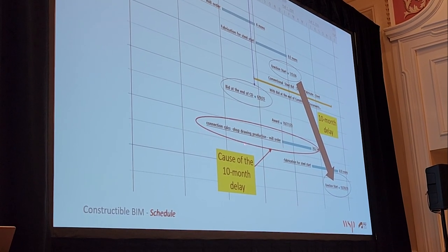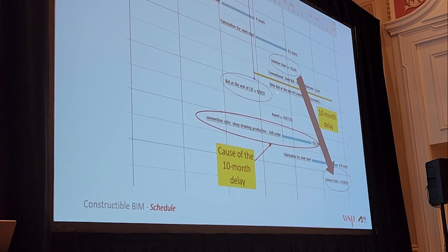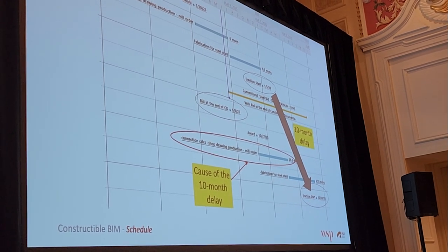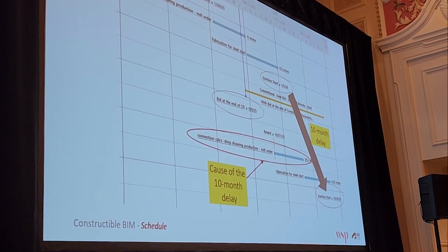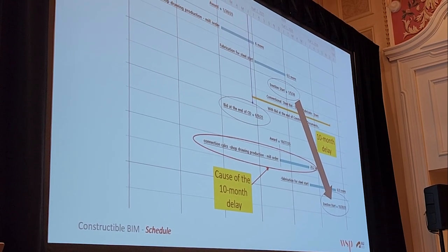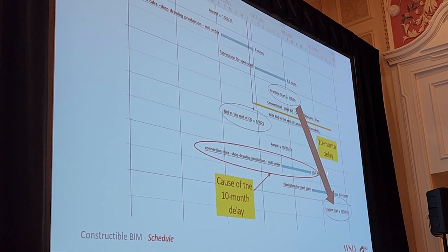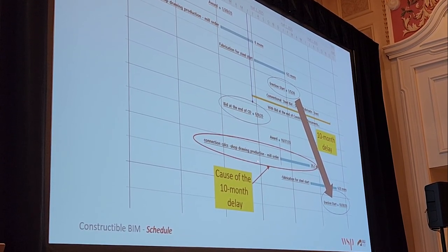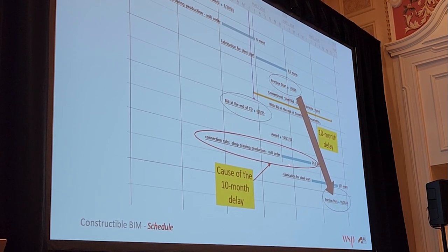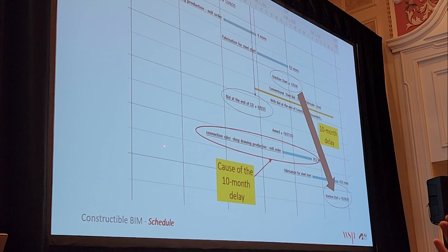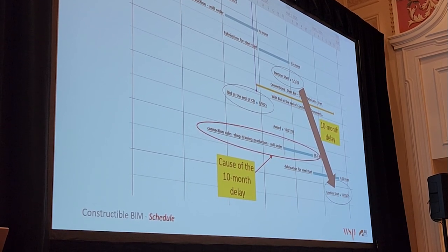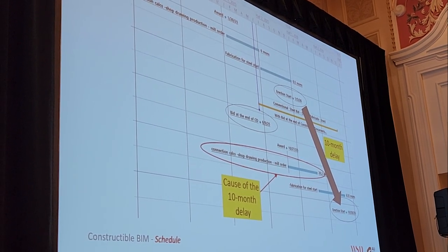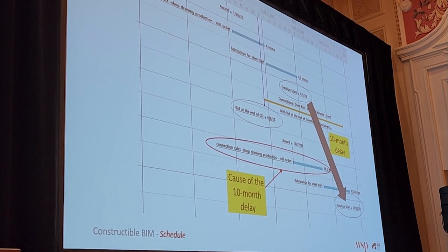Now, where are we here? And I'm saying, you could bid at the end of DD, you could bid at CD, bid whatever the client wants. But if you want to speed up the process, you take this out, connection calcs, shop drawings, and mill order, take it out. It's about half a year, and push it into the engineer of record's responsibility. And push it out and start it early. If you just push it out and let the engineer of record do it, you're not gaining anything.